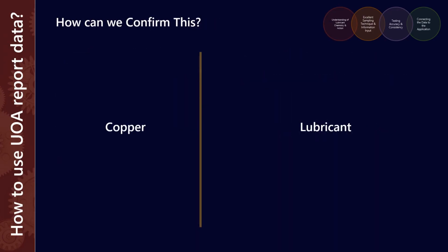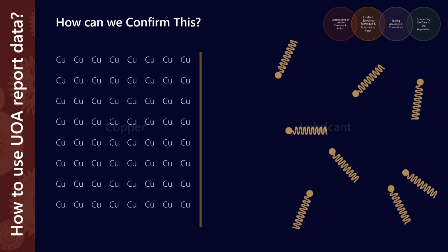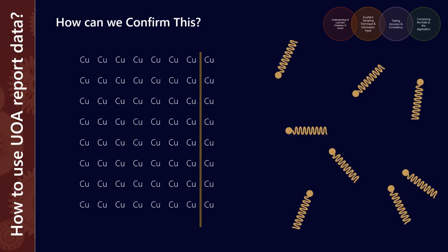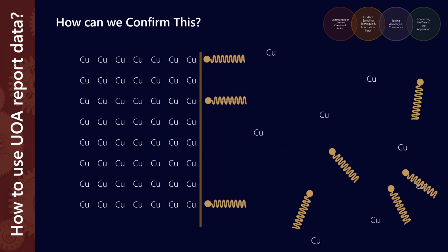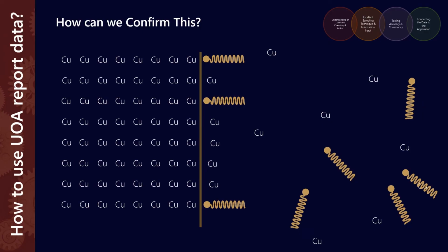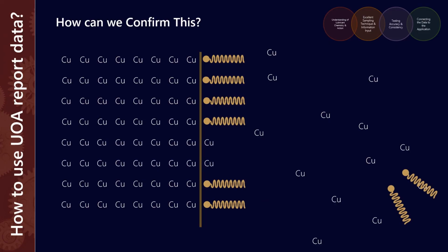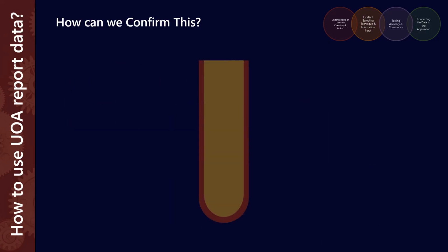So now I have to understand how the lubricant works with my copper coolers. I've shown this diagram a little bit before, where you've got copper on one side and the metal deactivators on the other side. Copper is going to want to bleed into the lubricant, I know that's not the technical term, and the additives, because they're polar, are going to bind to the surface of the metal to basically take up all those corrosion sites. As this continues, the surface area available for the reaction gets smaller and smaller. And that's why we see a decelerating pattern.